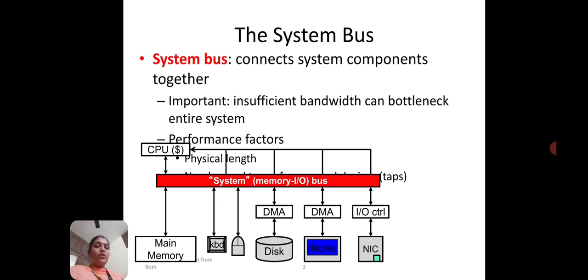The main advantage of using the bus is to eliminate the need for connecting every device with every other device, which avoids the wiring complexity that would quickly dominate the cost of a system. The main disadvantage is the slowdown introduced by the master slave configuration, the time involved in implementing a protocol, and lack of scalability. So these are the disadvantages of using a common bus.